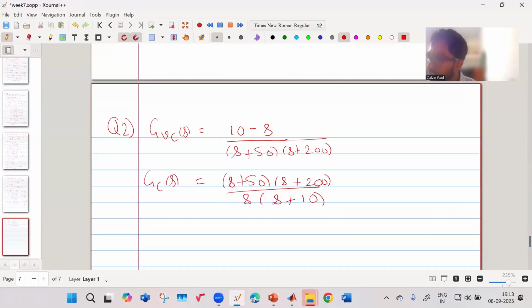And then what should I do? But phase margin equal to 60 degree also we need to achieve. So how do I make sure of that? Some other factor I need to add. What is that? Controller gain. Yes, exactly. K_I. So your controller gain.